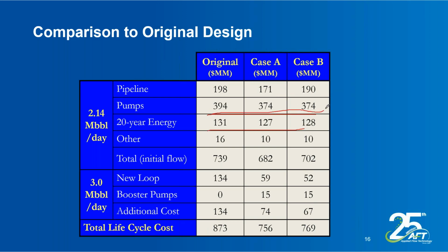So these are pump material costs, and these are the energy cost. And energy cost in the long run is always what dominates the cost of the project. So if you have the ability to start off with a little bit larger piping, that way you don't need as large of pumps, then you can experience much more cost savings in the long run than simply by trying to make your pipeline or your network as cheap up front as possible.